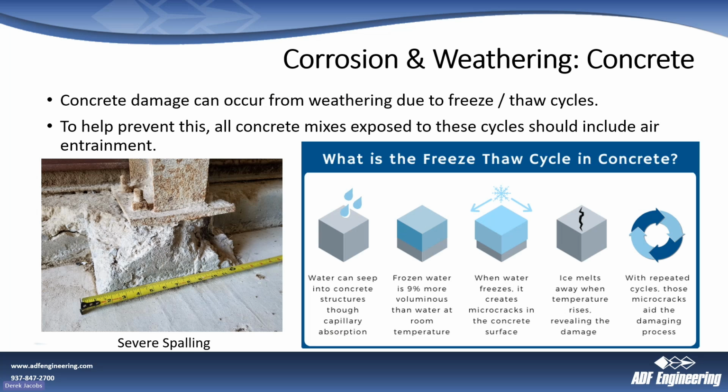So moving on to concrete, weathering is also an issue for that. A lot of times what you'll see from the most damaging part of concrete at our sites is what we call freeze thaw. This is a phenomenon with concrete where it's porous enough that water will get into the concrete.